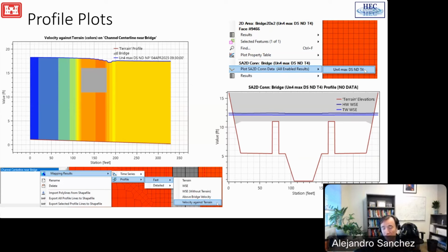Yeah, one note is, you need to put the bridge piers and abutments in the terrain. Now, the bridge piers, where do you end the bridge piers? Do you end them at the bottom of the deck, or do you continue them above? What I recommend is continuing them above to the very top of the deck, the high chord, because when you display your results in RAS Mapper, it'll show at least the flow going around those piers. Because if you don't, RAS Mapper doesn't know that there's a bridge deck there, and once the water goes above this level, it'll seem like the water's going through the piers. So I make my piers such that they go all the way to the high chord of the deck. It just displays nicer in some cases. In other cases, like this one, it would look a little weird. It just depends on what you want for plotting, but the results will be the same.